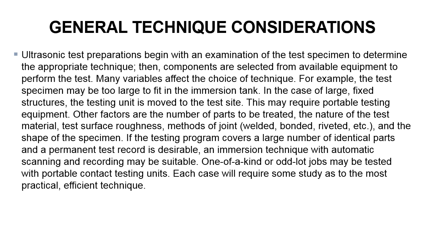Other factors are the number of parts to be tested, the nature of the test material, test surface roughness, methods of joining, welded, bonded, riveted, etc., and the shape of the specimen. If the testing program covers a large number of identical parts and a permanent test record is desirable, an immersion technique with automatic scanning and recording may be suitable.